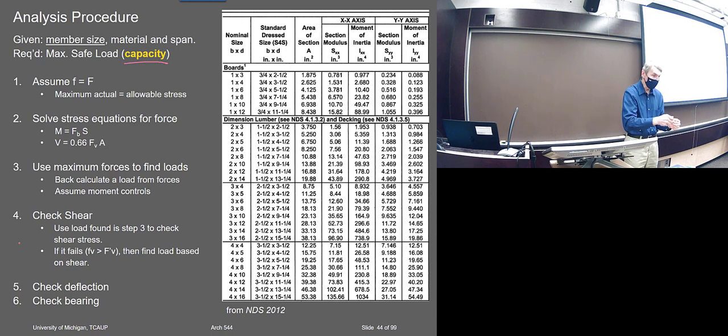Then installing it, you've got to nail all those things. Oh my gosh! And then just the logistics underneath at 6 inches on center. It's awfully dense to get mechanical stuff through, and so normally you would never go less than 12. Those are the options: 24, 16, and 12, or like I say, there's another one, 19.2, but it's an odd one.